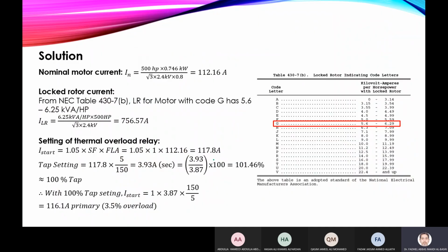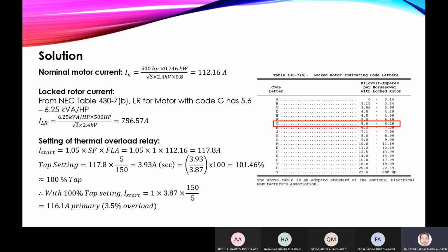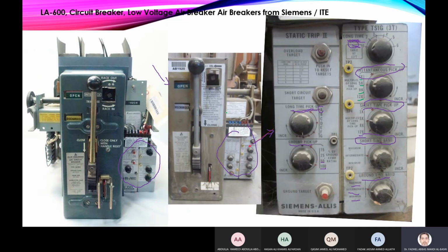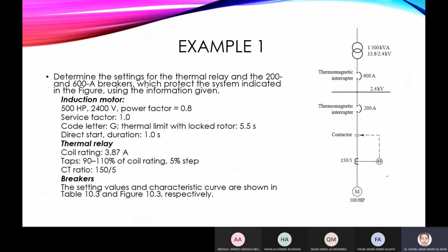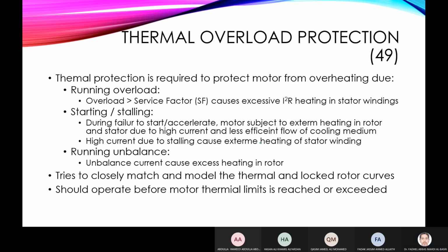Now, if I go to the solution, what will we start with? I will start with thermal overload. I will start with this one. This requires the full load current, to get the setting, as I mentioned, for overload.